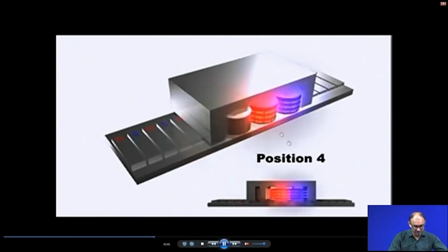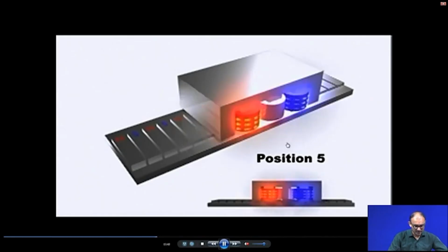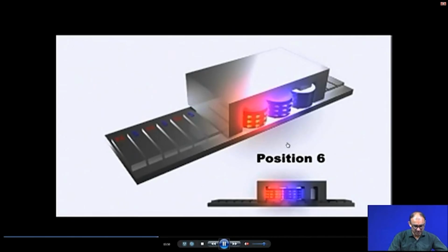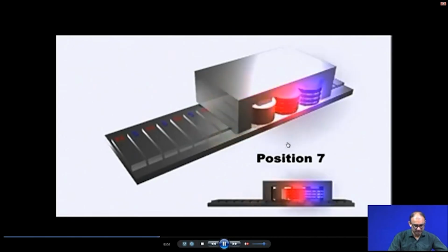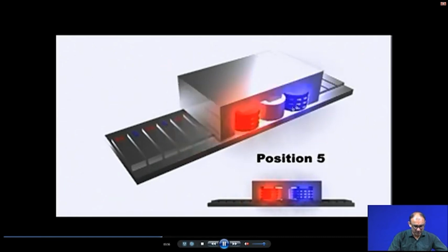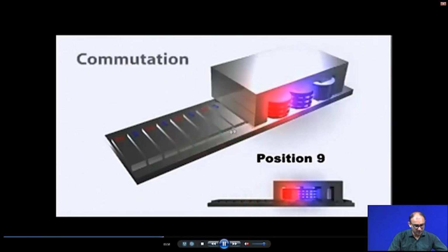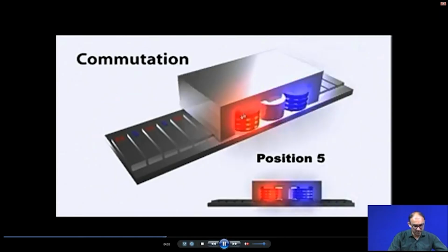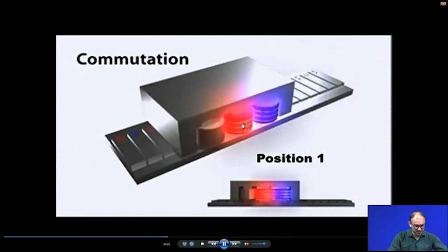So, this is the third position, this is the fourth position, and again the same thing will repeat. First the first two will be energized, then the first and the last one will be energized, and then the middle one and the last one will be energized. Correct. So, this way you can get the linear movement. Now if you increase that frequency of change, then you can get very high speed. This is the commutation, that is, how frequently you are changing the current direction.